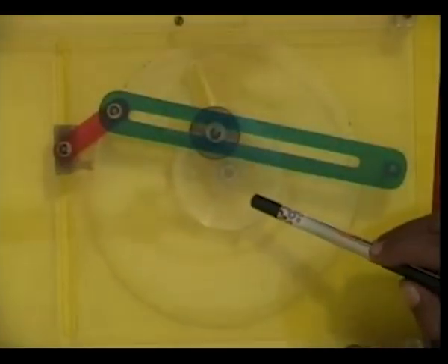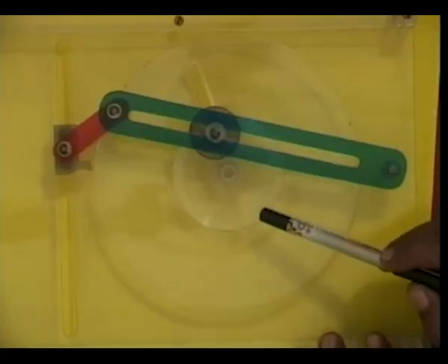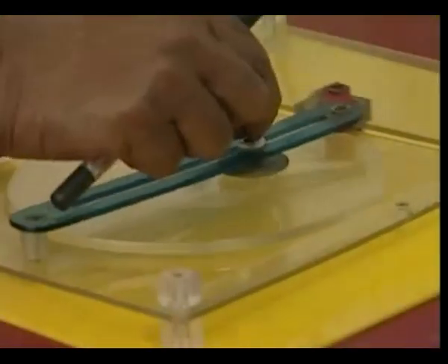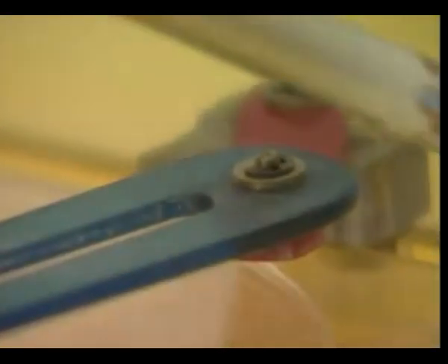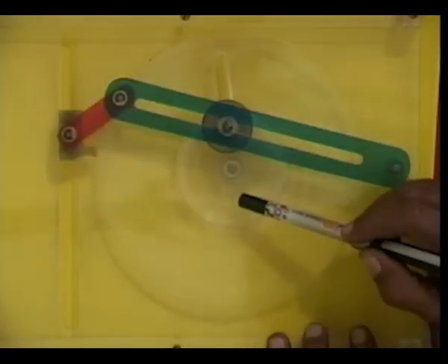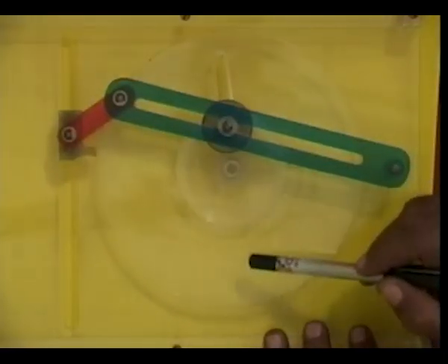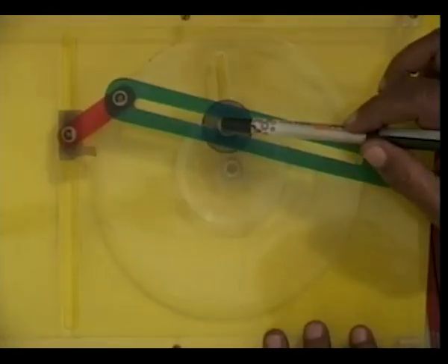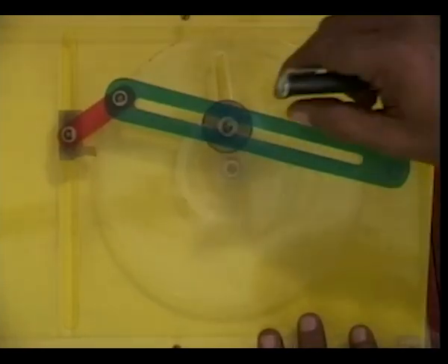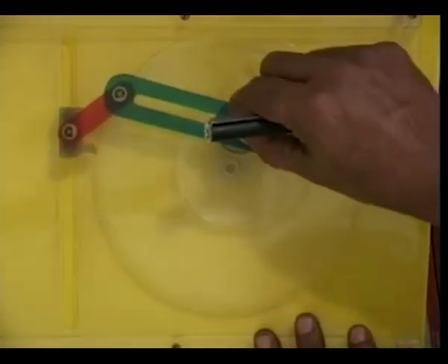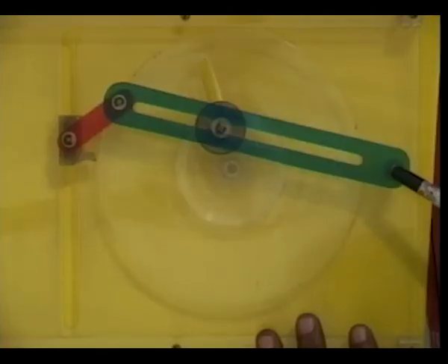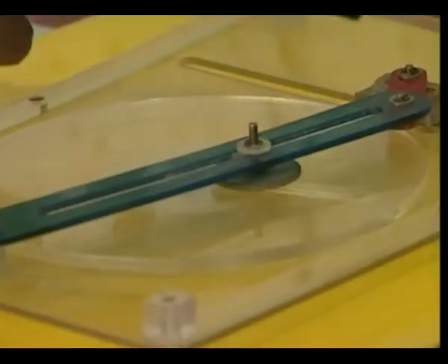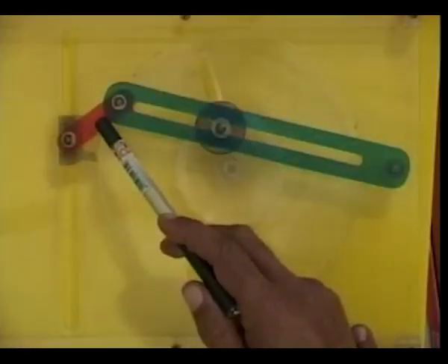This is the model of the quick return mechanism that is used in a shaping machine. This is the cutting tool. This tool holder moves in a slot in the frame of the machine. This is what is called the bull gear, which is rotated at a constant speed. And here is a block which is hinged to the bull gear, and this block moves up and down in this slotted lever, and the slotted lever is hinged to the frame at this point, and the slotted lever is connected to the tool holder by an additional link.